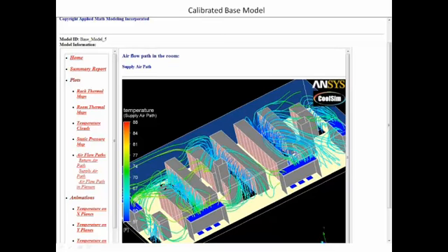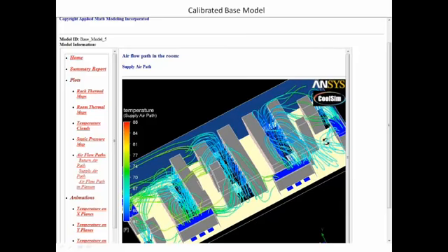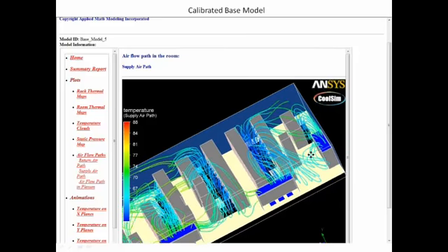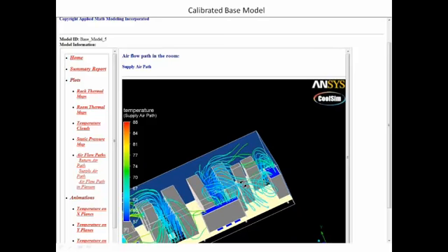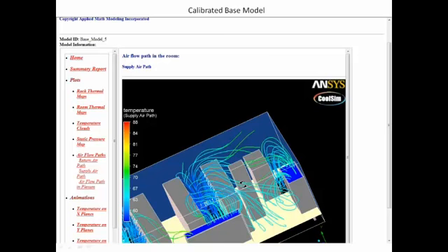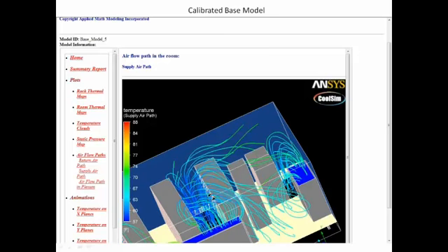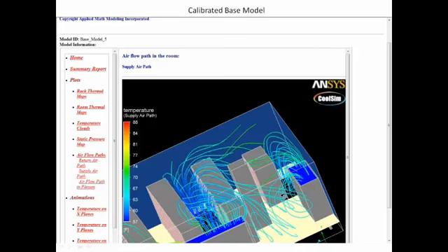It's coming back, and it's doing two things. It's cooling off the return temps, which is making a very poor delta T across these CRAC units, and you're spending a lot of money pumping it in the first place. I mean, look over here on this one on the far side of the room. They're just coming right up out of the floor, and it's not going anywhere. Ideally they should come up and go straight into the rack, but here they're going straight into this CRAC unit, which is not doing much work at all.